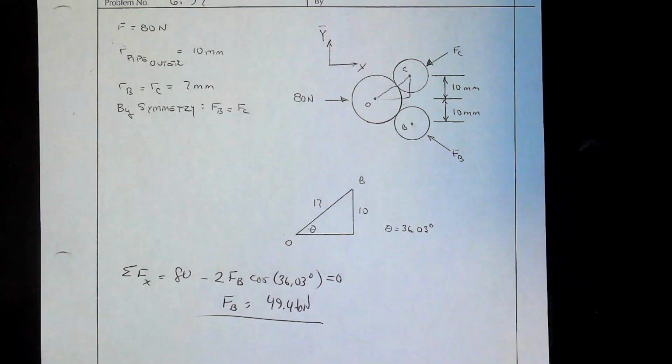And this is, if I look at the X component of this force, that's aligned with E, so that does nothing. I only need the Y. And if that's coming up relative to here, that's clockwise, so it's going to be negative FB. I need the Y component, so that'll be 3 on the root of 10. So that's all of the force, and it's 2 meters away. Again, set that equal to 0. Solve for FB. Come up with 1,939 newtons. So there we go. We just knocked that piece off.